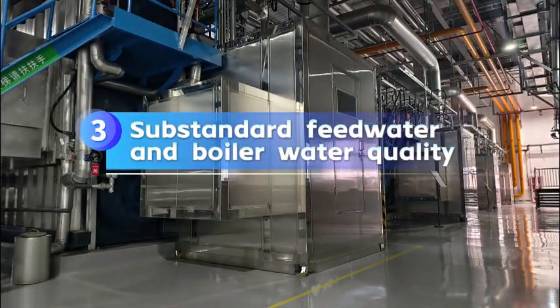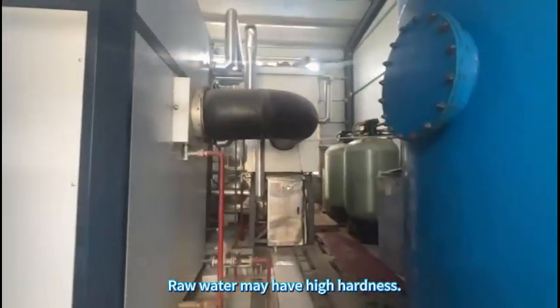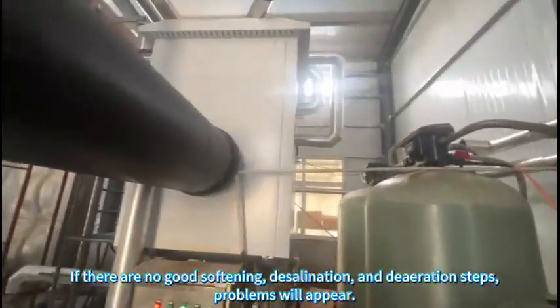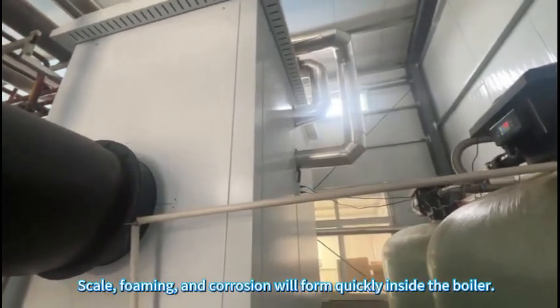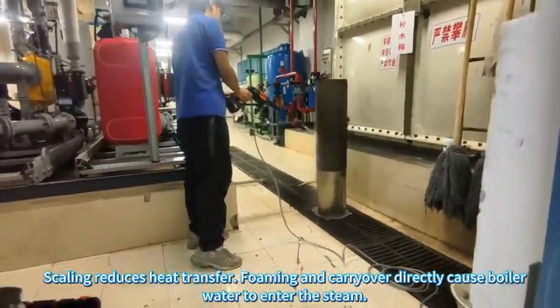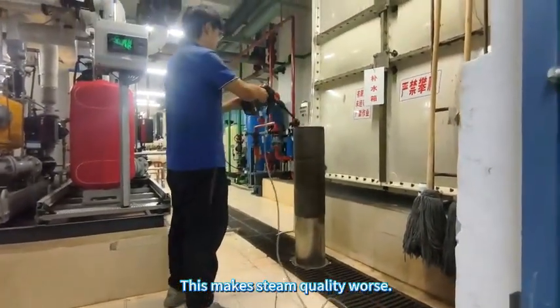Substandard feedwater and boiler water quality. Raw water may have high hardness. It might have high dissolved solids (TDS) content. If there are no good softening, desalination, and deaeration steps, problems will appear. Scale, foaming, and corrosion will form quickly inside the boiler. Scaling reduces heat transfer. Foaming and carryover directly cause boiler water to enter the steam. This makes steam quality worse.